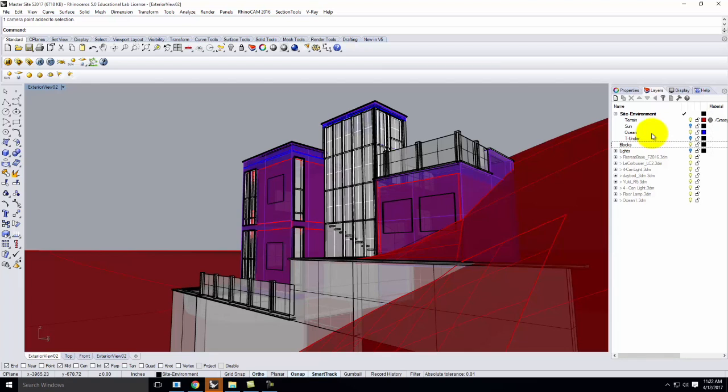Those of you that did take 135 and feel comfortable, substitute everything I'm about to say with Photoshop, clone stamp, grass brush. Okay? So, one of the important things, however, when you're thinking about V-Ray and actually rendering a particular scene is to control what is actually in the scene, and not have extra superfluous geometry that's sitting outside of it. So I'm going to start bringing in some grass to actually render, but I don't want a bunch of extra grass that's not in the actual view that I'm looking at. So establishing your view first is really, really critical.